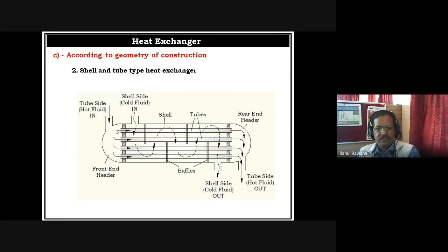Now imagine, suppose hot fluid is entering and passing through this tube, and cold fluid is entering into this shell, but due to this partition it can't move here. So cold fluid will enter, pass along the tube and move out, but during its pass it comes in contact for a very small time period, so it can't gain that much heat.